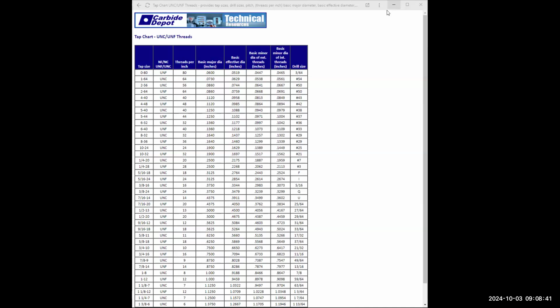All right, I'm going to put snap angle back to 0. And I'm going to delete these lines here. And I'm going to change this line, this line, this line, enter, type in P for property, LT for line type, hidden, enter, enter again. So it's hidden. All right, now Mr. Morris is very happy. Whew. I hope you have all the holes.